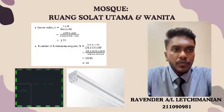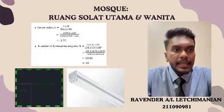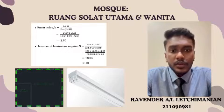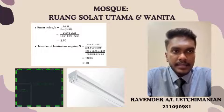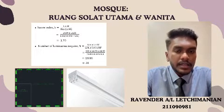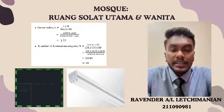First of all, we need to find the room index, which is K equals length times width divided by HM times (length plus width). So we get K equals 1.70. The COU we choose is 0.59 according to the datasheet for the TLD standard 3 times 36 watt. The value of COU is the brightest as we choose the brightest fluorescent color.